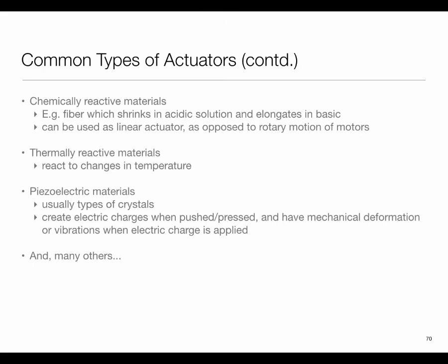One thing is that controlling an actuator tends to be pretty timing sensitive. So things like PWM usually have hardware support. You can tell the hardware unit, I need a PWM waveform with this timing characteristic, and it takes care of it. Because otherwise, doing it in software yourself all the time can be pretty expensive. As you do some of the homeworks where I ask you to generate waveforms and all,